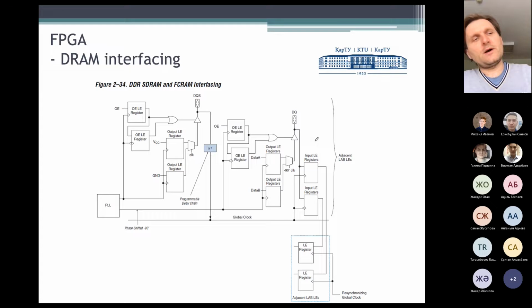The special part of the FPGA can manage that DRAM, and the FPGA and microprocessor, which is inside that structure, see that memory as a static RAM. So these kinds of procedures are done in that FPGA to make it easier to work with that memory. The DRAM is cheaper than static RAM.